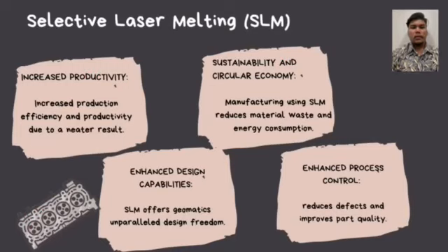Now, I want to talk about the key features of the machines used to build the cylinder head. To create the cylinder head, two machines and two processes are used. The processes are selective laser melting (SLM) and CNC machining. The first is SLM. Selective laser melting is an additive manufacturing process that uses a high-powered laser to select, melt, and fuse metal powder layer by layer, which is a broader category of metal 3D printing.